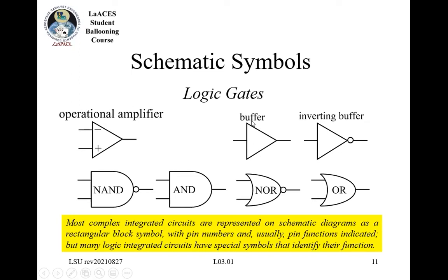Sometimes it's good to have a buffer with electronic circuits, and that's mainly because say that you have signals coming in from the outside world. So say you've designed a board and somebody is going to use it, and you want to protect your electronics, maybe your microcontroller, or you have an embedded processor or FPGA, then it's really great to use buffers to protect those more sensitive circuits. And so that's just one of the many reasons why you might have a buffer.